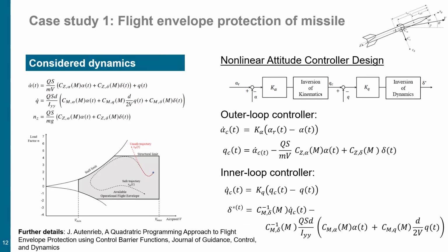You see alpha dot here, right? And alpha dot has this term CZ delta, right? So there is already a delta term in alpha dot, but I still, with confidence, said that I did something with alpha dot dot, right? And alpha dot dot is a function of q dot, and there is your term cm delta delta, right?